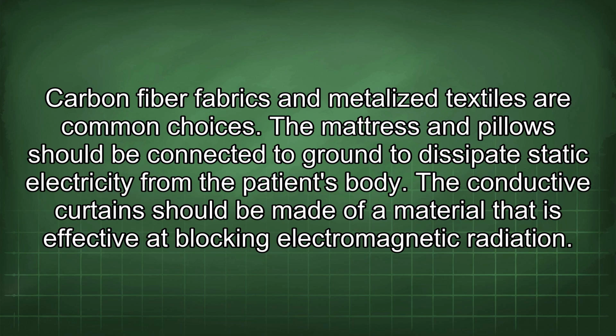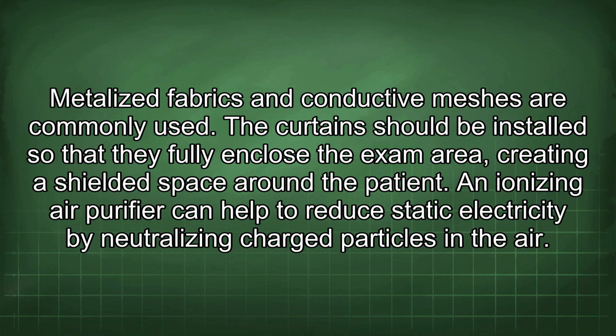The conductive curtain should be made of a material that is effective at blocking electromagnetic radiation. Metallized fabrics and conductive meshes are commonly used. The curtains should be installed so that they fully enclose the exam area, creating a shielded space around the patient.